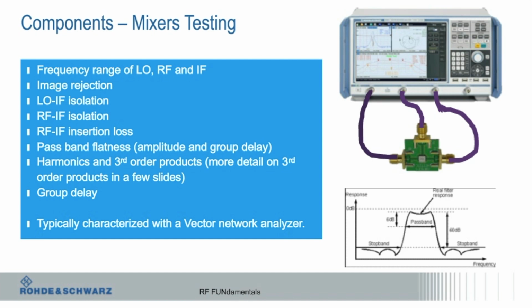So basically, signals bleed through that you don't particularly want to get there, and you have to be aware of those. The challenge when you design with mixers is you get lots of frequencies out. Typically you'll say IF is RF minus LO. Boom, I'm done, everything's good. The unfortunate reality is that's not all you get. You get IF is also RF plus LO. You get 2RF minus LO, RF minus 2LO, and so on. All the integer multiples of all those things will show up.